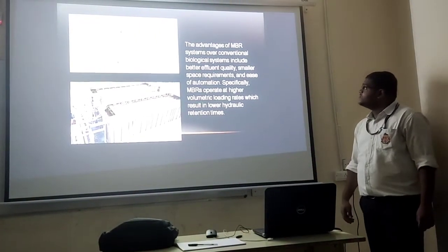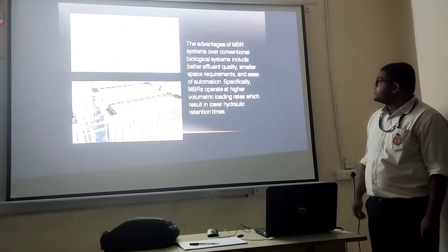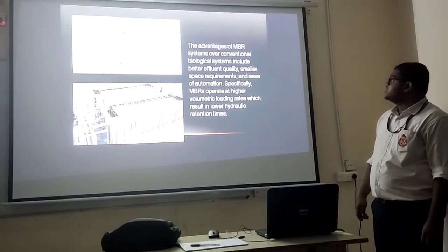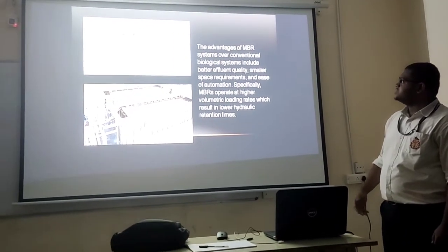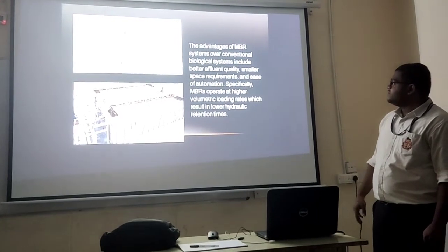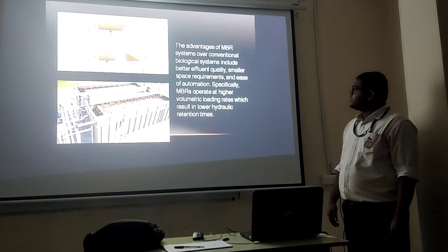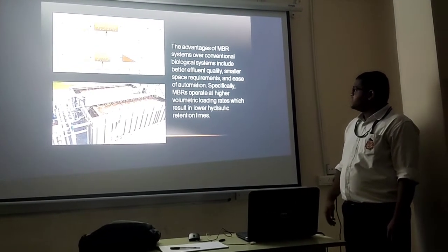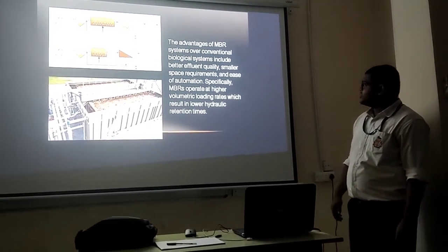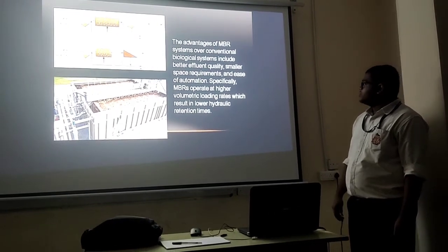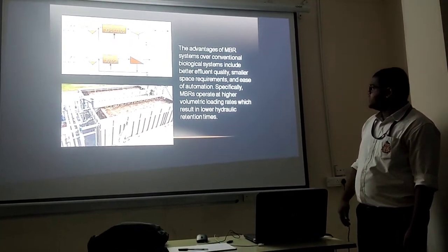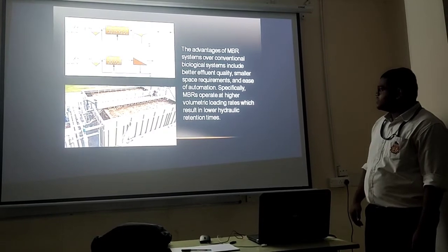The advantages of membrane bioreactor systems over conventional biological systems include better effluent quality, smaller space requirement, and ease of automation. Specifically, membrane bioreactors operate at higher volumetric loading rates, which results in lower hydraulic retention times.